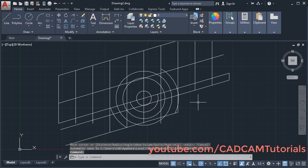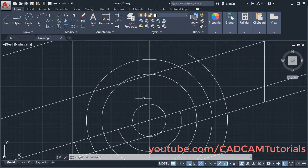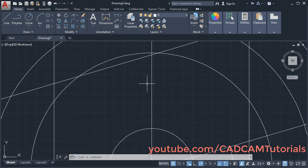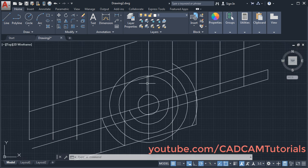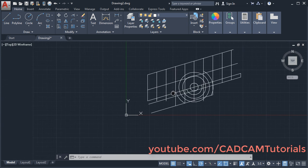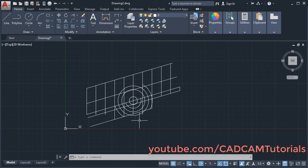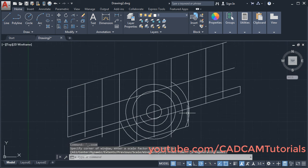Then we have seen zoom and pan. For zoom you will have to rotate your middle mouse button or wheel towards the monitor, so it will zoom plus. If you rotate the wheel towards you, that will make it zoom minus. Then if you press the middle mouse button and drag the mouse, then it will be pan. And if you want to zoom extend, just double click the middle mouse button. It will zoom extend the drawing.